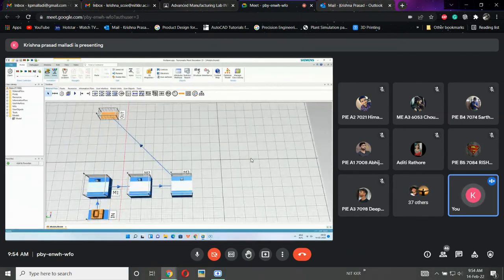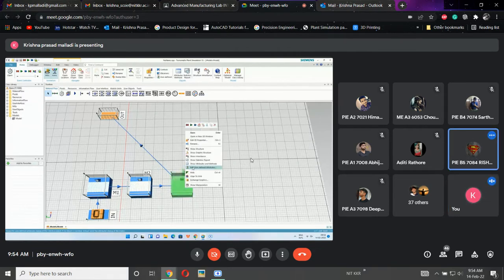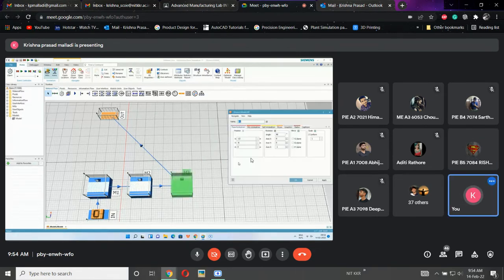Same. If at all I want to change, I can change these labels also. Clear? How to change the labels? We will go into edit 3D properties. In that, instead of transformation, we need to enter into captions. Here you can place accordingly.